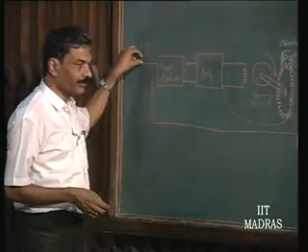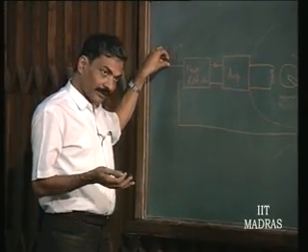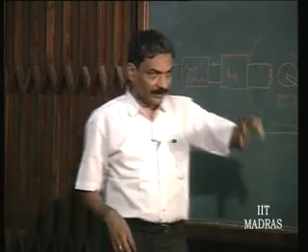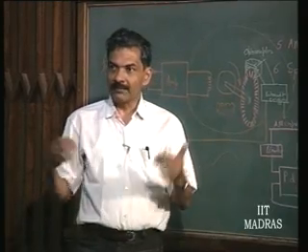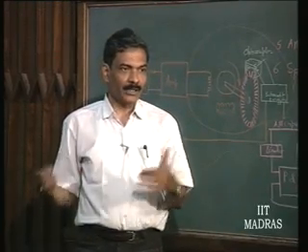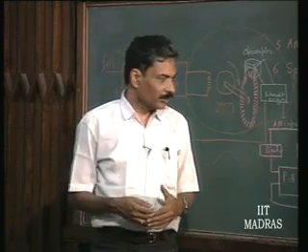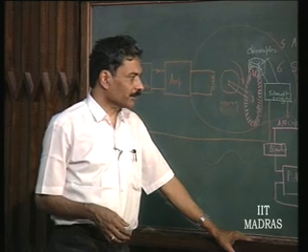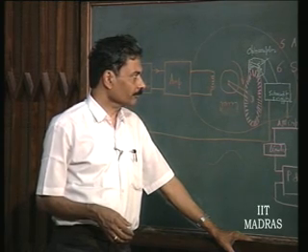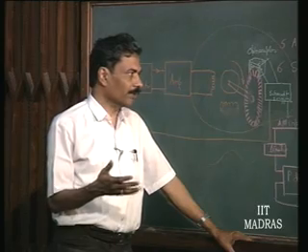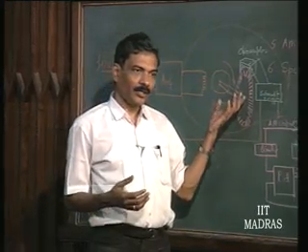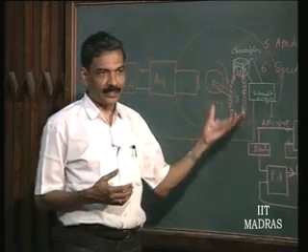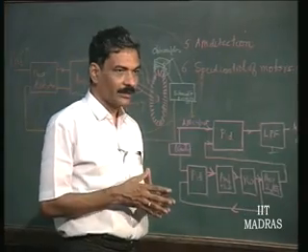And this frequency is going to be extracted once again from a crystal oscillator frequency coming through a frequency synthesis network, okay, which again will comprise of phase lock loops, multipliers, phase detectors and others. So, you can see that this whole scheme is very interesting, and this you can try out for any of your small motors, okay, in the laboratory itself. There is no difficulty in trying out this kind of speed control schemes in laboratories.